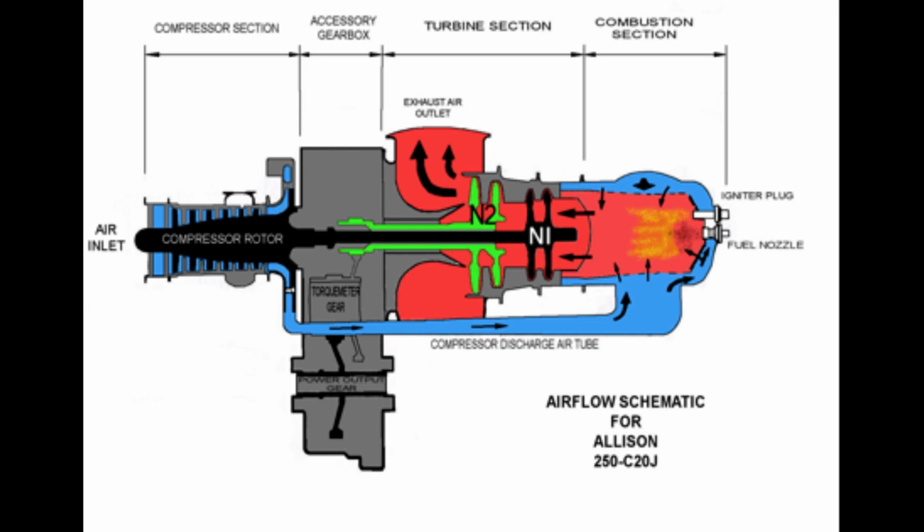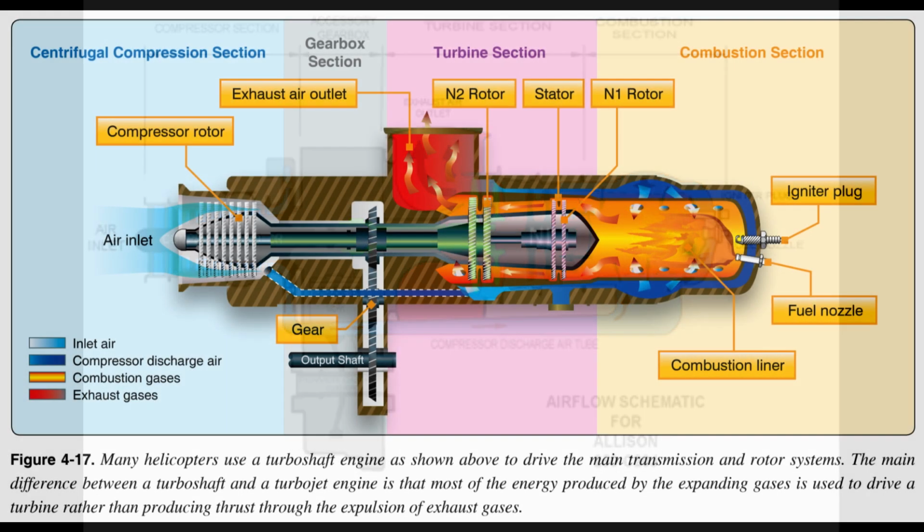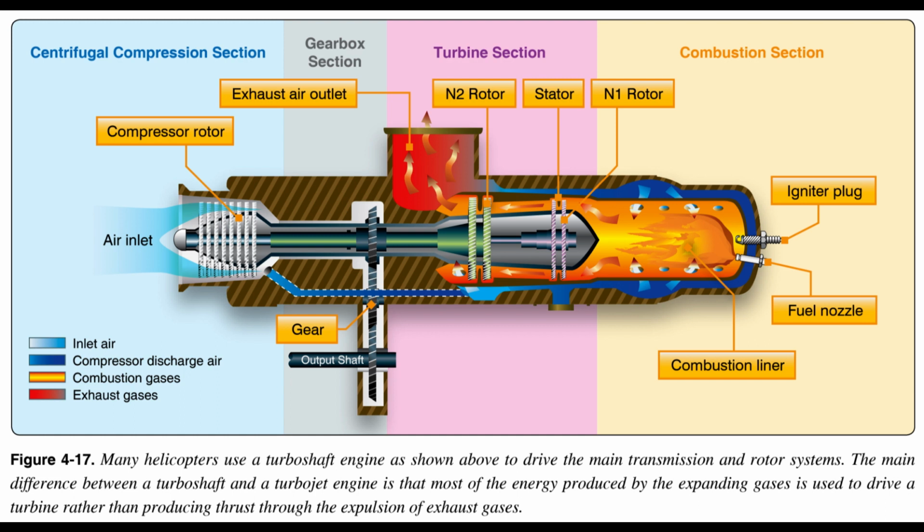End of page 4 to 8. Although this design significantly reduces the ingestion of foreign objects into the engine, it is important for pilots to be aware of how much debris is actually being filtered. Operating in the sand, dust, or even in grassy type materials can choke an engine in just minutes.